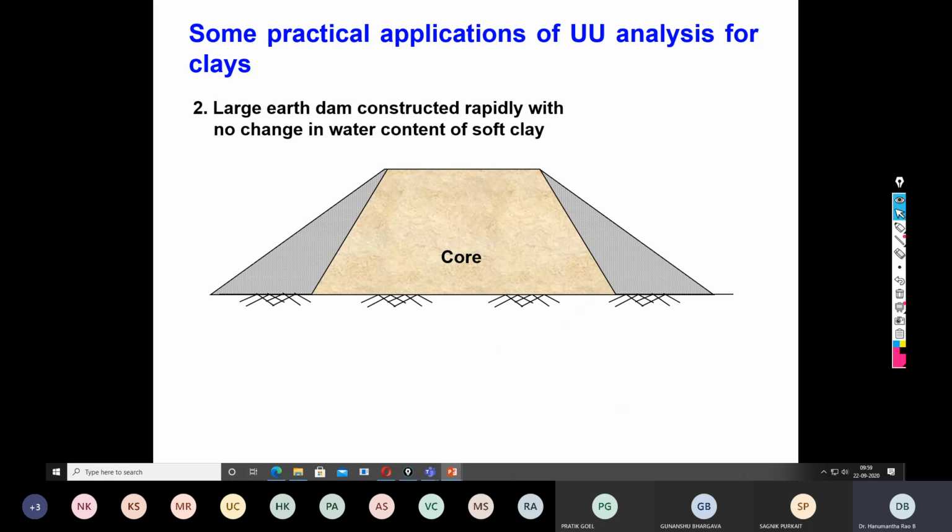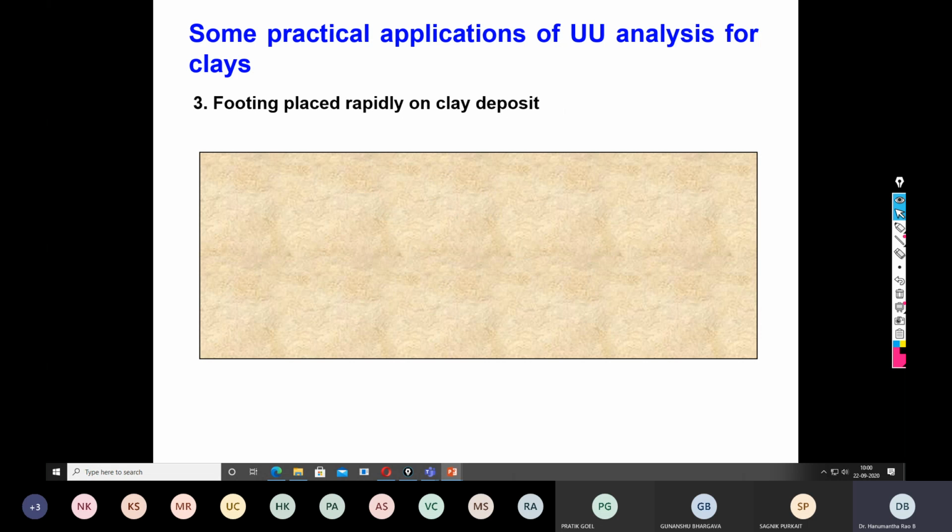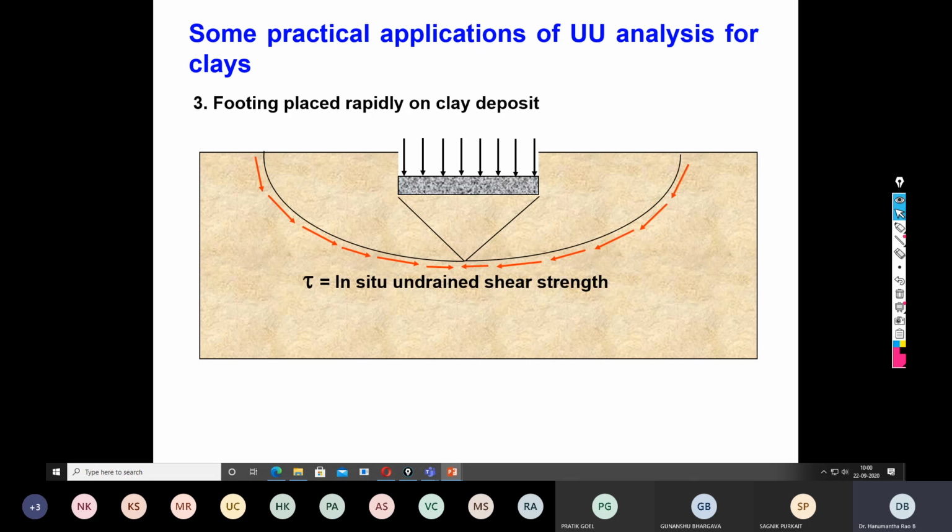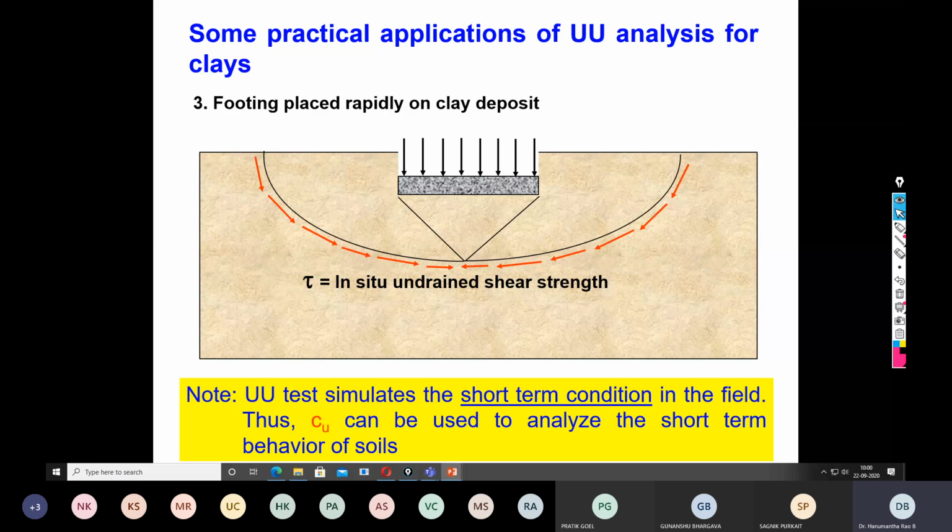The same thing in the case of a dam also during the construction, so the unconsolidated undrained condition develops. Undrained shear strength of the clay. Then similarly a footing. Initially undrained condition develops. As the delta sigma remains the same, that leads to consolidation of the soil sample, leading to development of the CU condition. Then once the whole water gets drained out, it further leads to CD condition.